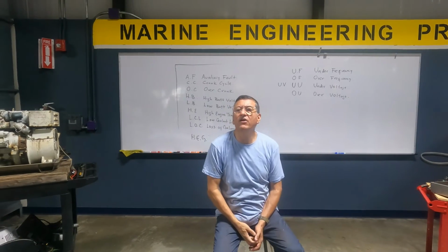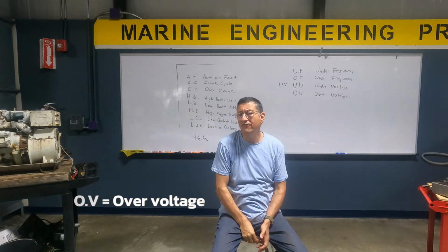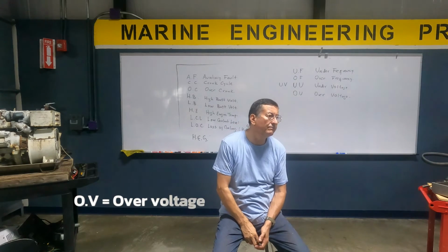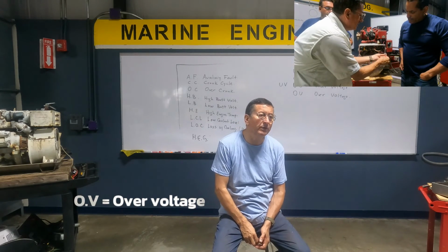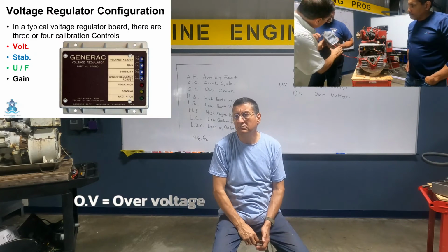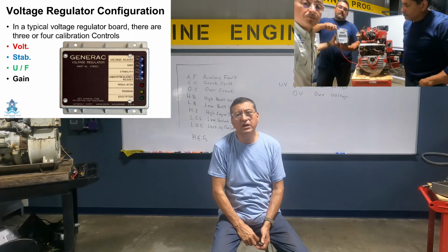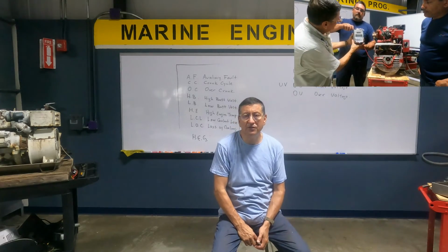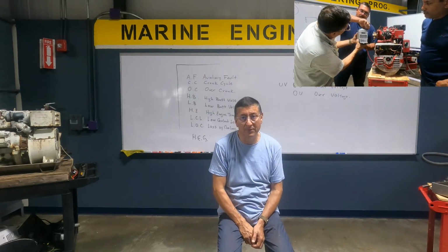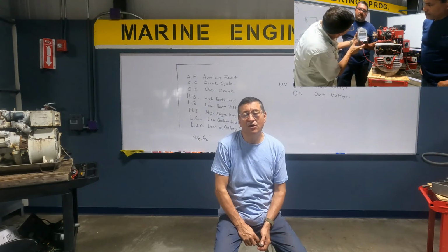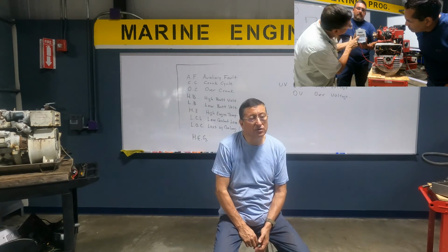The next one is over voltage or high voltage. Exactly the same as the previous one. If it's small, you can calibrate with the voltage regulator. If it's ultra high, you have 2 possibilities. One possibility is to check the neutral, remember? And the other one, of course, is to check the condition of the winding.